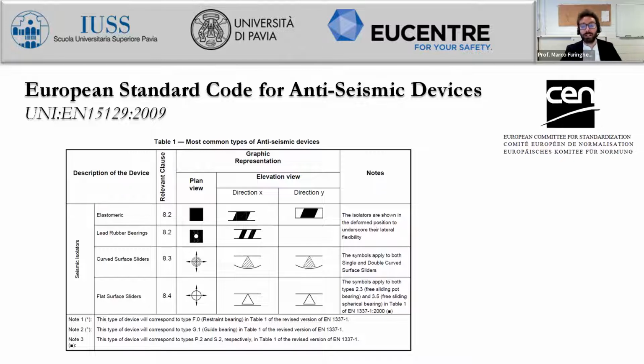But for elastomeric bearings, according to the mechanical properties which are returned by design procedures, it is quite uncommon to find an isolation system based just on rubber bearings, but we need hybrid systems, so together with flat sliders. Actually, it is not possible to use hybrid systems with curved surface sliders because, first of all, generally, these kind of devices can lead to the proper design definition with actually the same bearing everywhere.